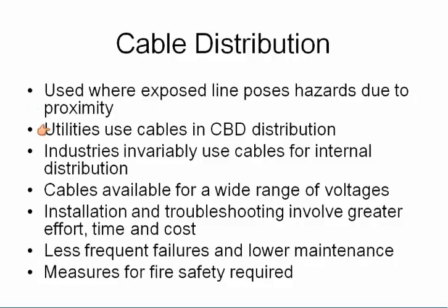Cables are used in the CBD, Central Business District, to avoid exposed line and pole hazards due to proximity. Industries use them for distribution. In terms of installation, it's expensive. Also, if there is a cable damage, although it is unlikely, less common than overhead lines, it's hard to find it out. However, you have lower failures, lower maintenance, and in terms of environmental issues, you're not prone to lightning storms or other issues that overhead lines are subject to, bushfires and so on.